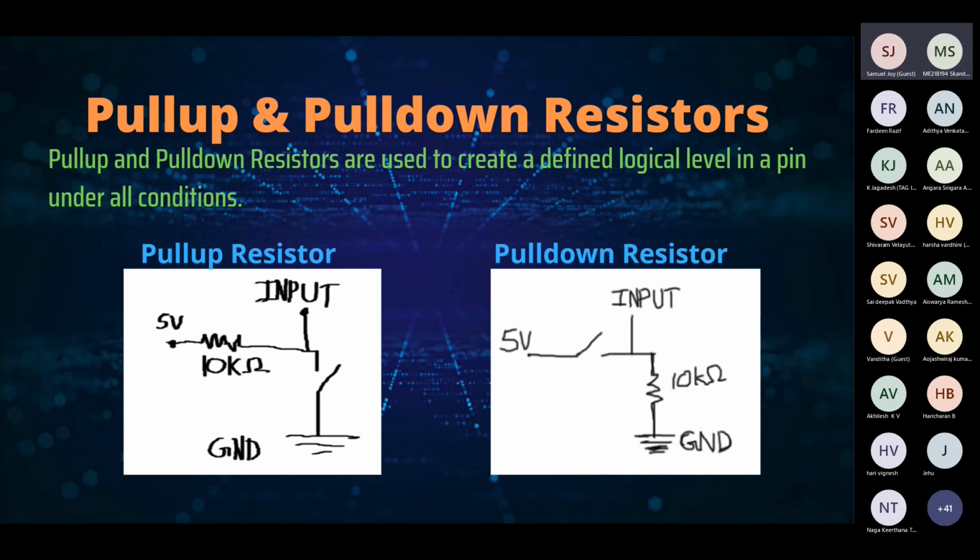And this input, when the switch is in off position, can take any value between the highest voltage possible, 5, and ground, which is not often expected from a device point of view. So basically, it can take any value and it can change from one value to another directly. So these resistors prevent that from happening by allowing this to be connected to a potential.